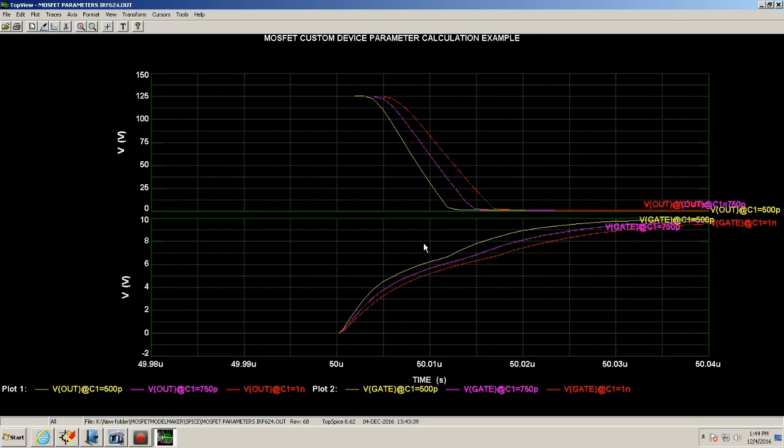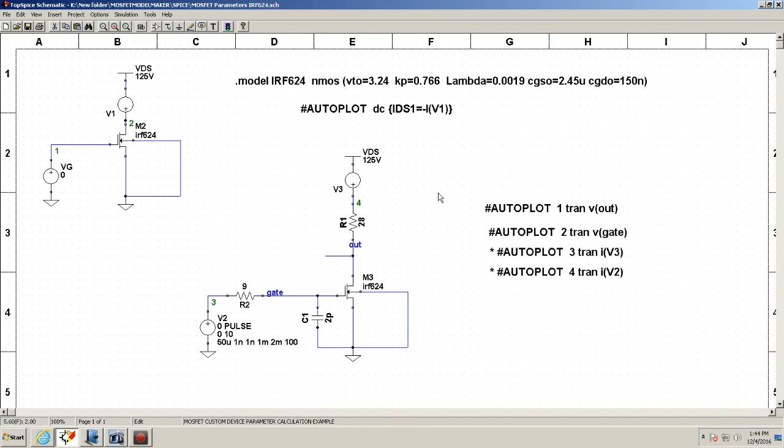Adding capacitance from gate to source doesn't particularly speed up or slow down your drain to source as much as it does the delay time, but it does change the first, second, and third intervals. So that's what I wanted to show: as far as delay time, the Miller cap by far has more effect versus a small change in capacitance.